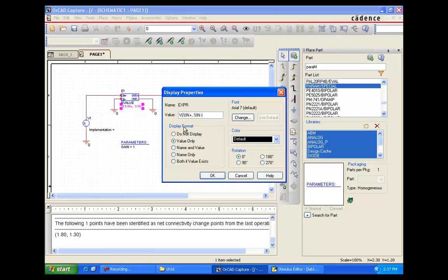Now in this circuit we're going to have an expression for the property. The expression we have to make is V input percentage, so we have to change the average to ABS and change it to ABS V percent input plus, percent input minus, star gain. So this should be multiplied by the absolute value of whatever the voltage at the plus input and minus input is, multiplied by gain, and ABS is absolute.